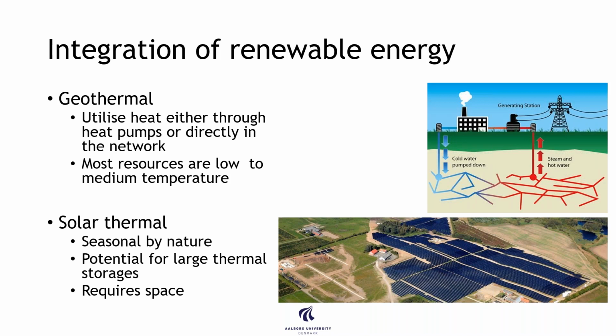If we look at it globally, most resources are typically low to medium temperature, so they could require a heat pump to be sufficient. Another option is solar thermal. Obviously, here we have the risk that this is seasonal by nature, meaning that most of the solar thermal energy comes in the summer, and you most of the time need your hot water and heating mostly in the winter. So here there's also a potential for large thermal storages.